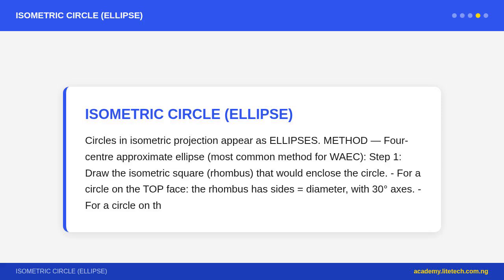5. Complete the box by drawing parallels from each endpoint. From the end of the 60 mm edge, draw a vertical 30 mm. From the end of the 40 mm edge, draw a vertical 30 mm. Join the top edges along the 30 degree axis to close the box. All edges are parallel to the 3 axes.